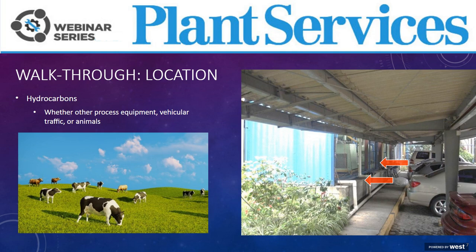So this is one of my favorite slides, and what goes in has got to come out somewhere. So in addition to where the compressors are installed in the plant, you have to consider where the intake air is actually coming from. Compressors ingest ambient air, and this air is going to come out into your plant processes. If your compressor room is located near exhaust fumes, like the picture at the right, or other contaminants, possibly like what we see in the picture at the left, those contaminants have an opportunity to be passed on to the end use. Certainly, filtration can be installed to remove hydrocarbons. However, this is an item that must be considered during your design phase.